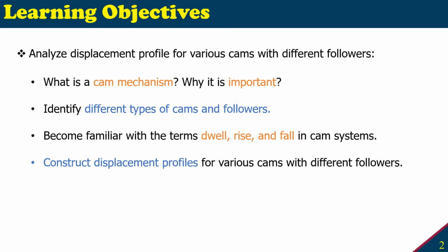Then we'll familiarize ourselves with the cam system terms that we use for cam mechanisms, such as dwell, rise, and fall. And finally, we'll do the experiment with 4 different types of cam mechanism to construct the displacement profile for those mechanisms.